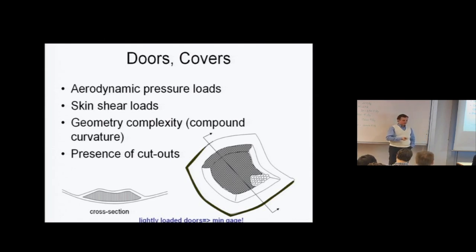In composites in particular, because of the moisture absorption concerns, if you make your structure very thin, on the order of 2 to 3 plies, each ply being on the order of 0.15 millimeters, then over time, especially in a humid environment like the island of Guam, you will actually absorb a lot of moisture. This moisture goes through much more easily and can cause all kinds of problems, not only by reducing the local stiffness because the structure swells, but also because if you then freeze that moisture, it expands and it can cause all kinds of additional problems.